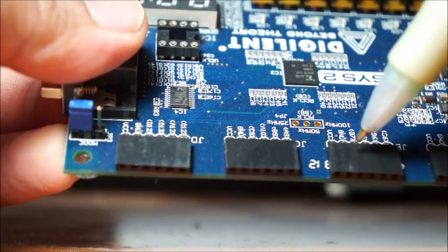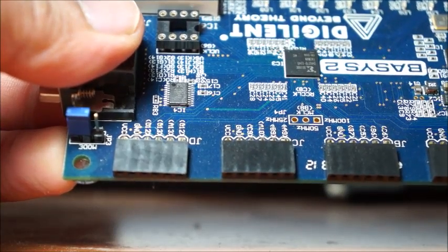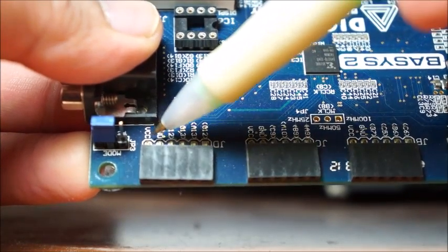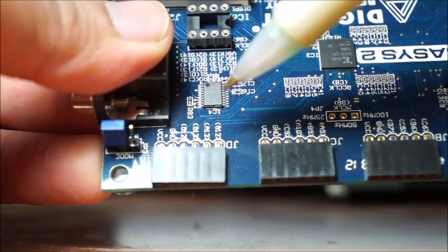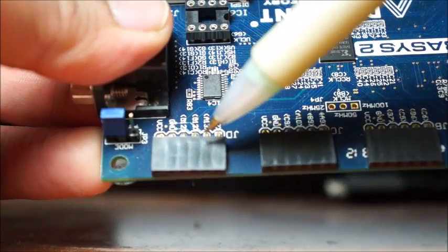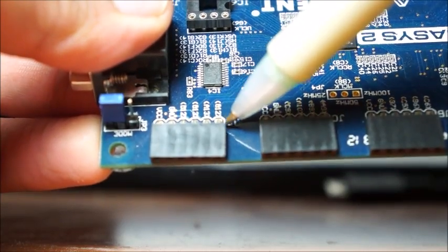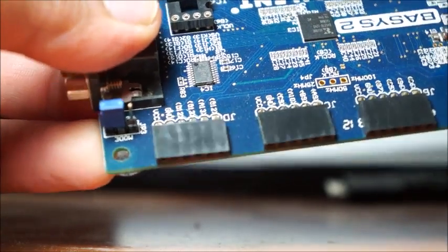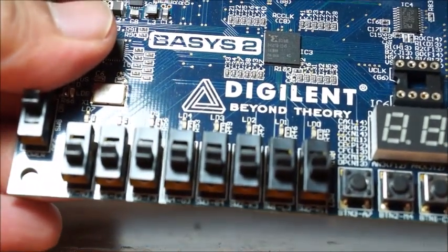Also make sure you never connect a high power load to these pins. Always put a level shifting circuit in between them. In case of a motor, you want to connect the H bridge to the FPGA and not the motor directly. So make sure you keep these things in mind, and good luck with your programming.